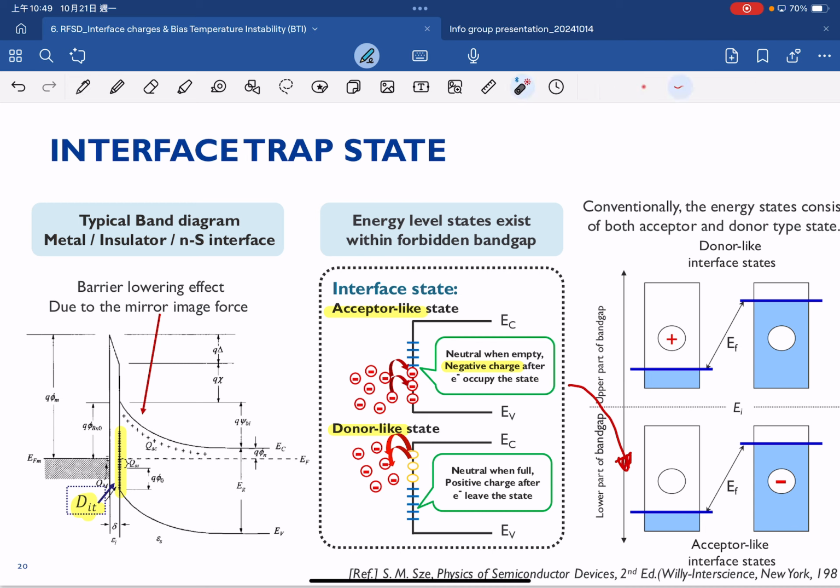Now you have to use some imagination, because this is a graph that combines the band diagram and the trapping site. First, where's the band diagram? This is the Fermi energy, our EF, inside a certain semiconductor material. But now, if your trap level is here, then in this case your EF is below your trap energy level. So this is usually considered neutral.